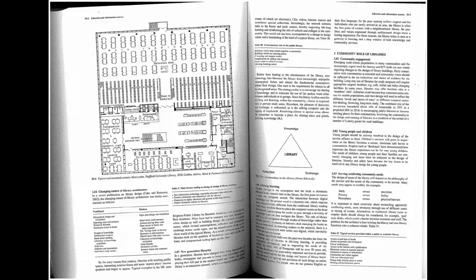How are you able to apply the design language rules of that trabeated facade, because you want a classical appearance through your library, back in through Part L of the building regulations to make sure you have a thermal gap between those facade parts and internal parts, and then moreover those internal parts that have to house conservation collections that are totally separate, or such invaluable collections that must be secure and avoid any risk of theft. So these many levels and separations are parts which are critical to then lay out and explain as principles that are important to you.